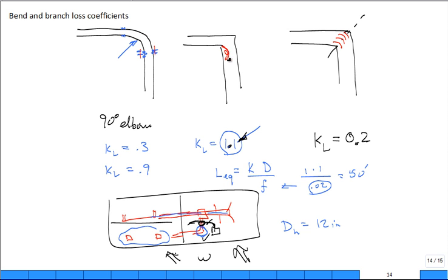It's going to separate here, right? There'll be this whole region in here. And I think also there was a takeoff for a duct that went this way, one place. I think in my illustration there was a bedroom, and they took off right here and fed that bedroom. It was right after, close to the turn. You're not going to get good airflow to go in that leg. It's the wrong way, coming over after that 90 degree to try to go this way and have to feed the grill in that bedroom right there.